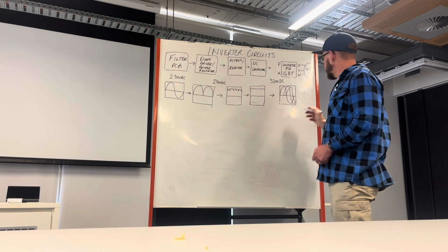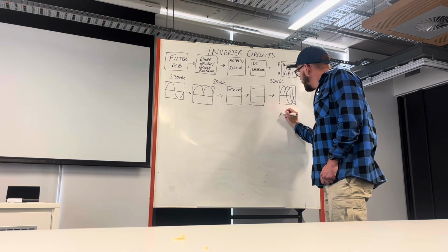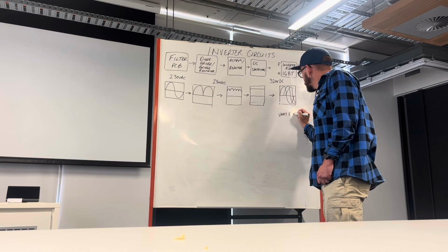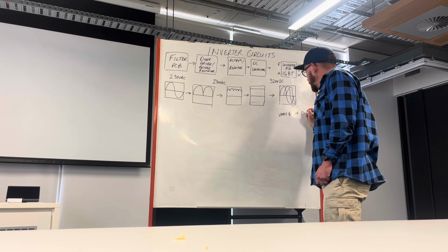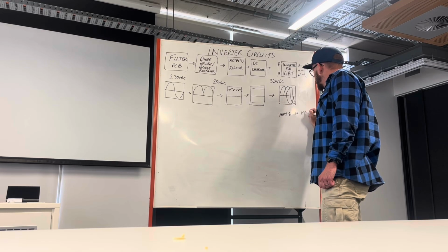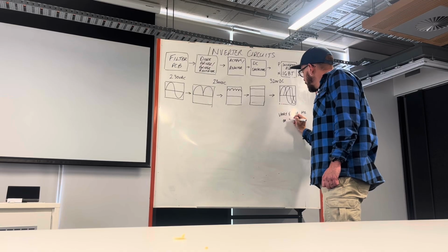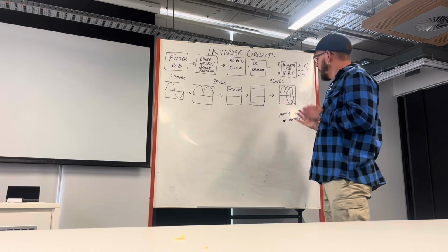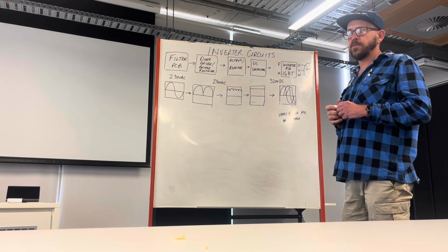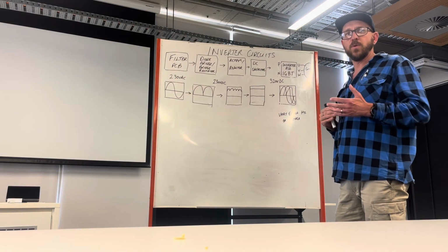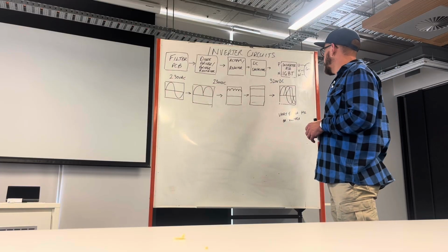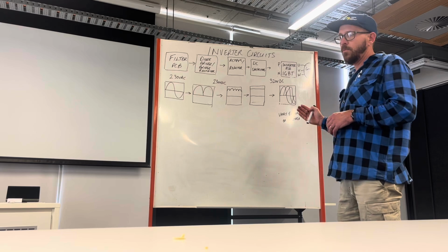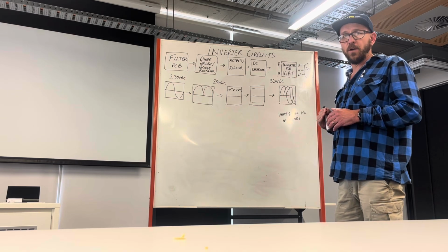Now we can vary either the frequency, the hertz, or the voltage to ramp that compressor up and down, and that gives us control rather than the old systems where we'll direct online, compressor just banging in maybe with a soft start or a capacitor, running till it gets to temperature and turning off.